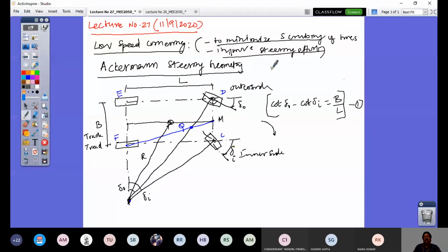So when there is no centrifugal force, I neglect the lateral force requirement, and that lateral force, you know, is because of C alpha into alpha. So when there is no centrifugal force, this is zero, and there is no slip angle. So it's only the steering angle at low speeds.